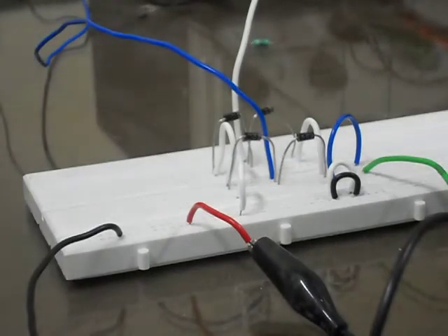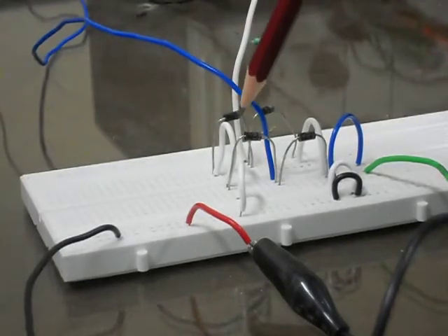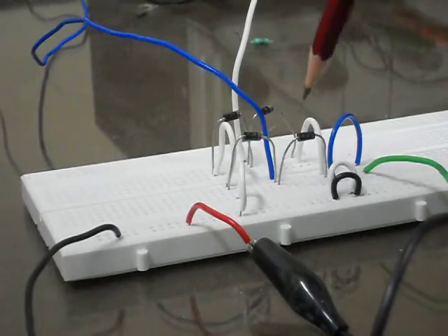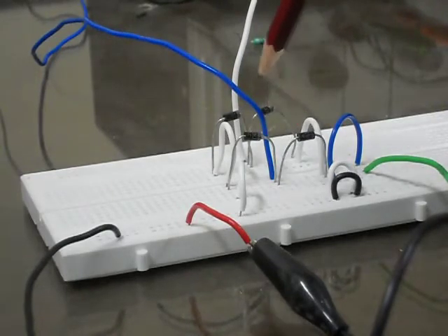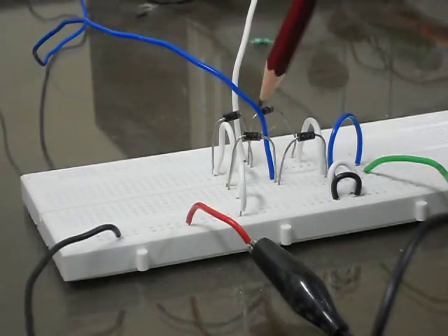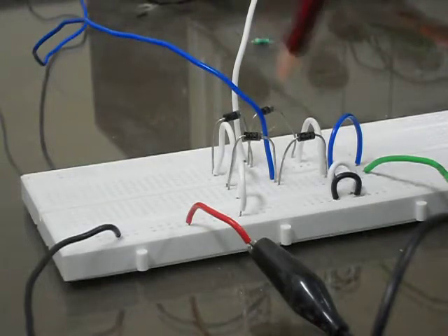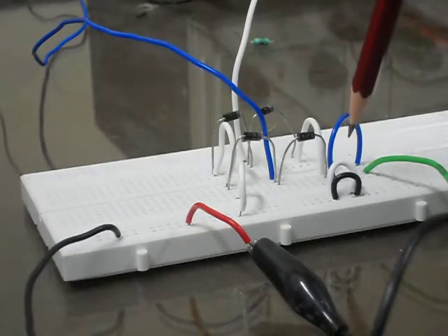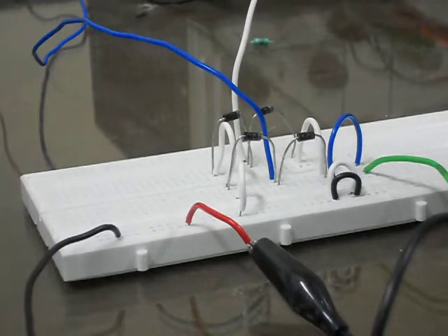What I have here is the bridge rectifier. So these are my diodes 1, 2, 3 and 4. Out of the 4 ends, one end is connected to ground. At the two opposite ends I have the output from my transformer, which is approximately 40 volts peak to peak, as we saw in the last video. And the last end is my output end, which I'll connect to the capacitor plus further circuitry, right? So this is my bridge rectifier.